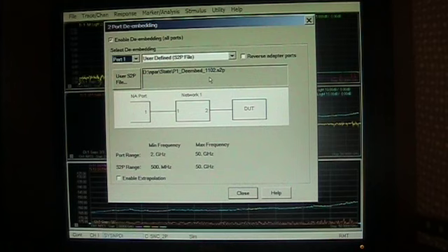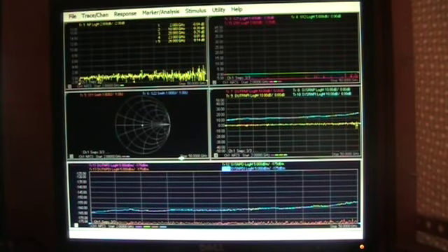Every time the tuner moves, the controller code will go to the library of de-embed files that were captured during the tuner calibration process. We'll just keep dropping these in. So although the device will be presented a different reflection coefficient every time, the measurements will remain corrected through the de-embed process. So in essence, there's no additional math that needs to be performed on the actual noise figure measurements that come out of the instrument. We can go directly to an extraction once they're captured. So this state file has been saved.